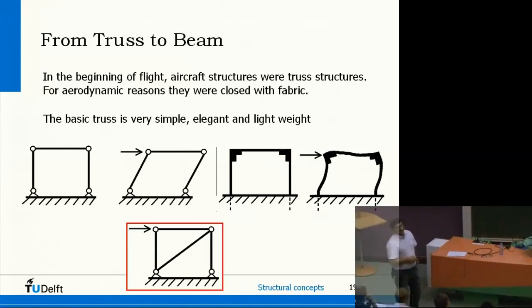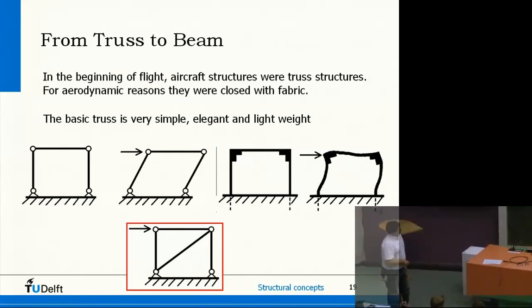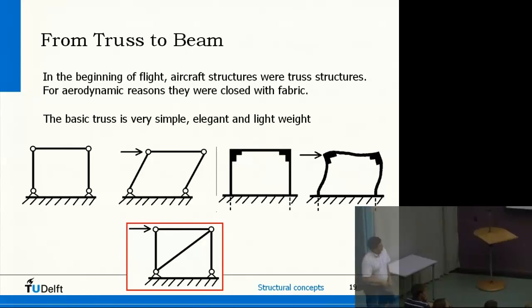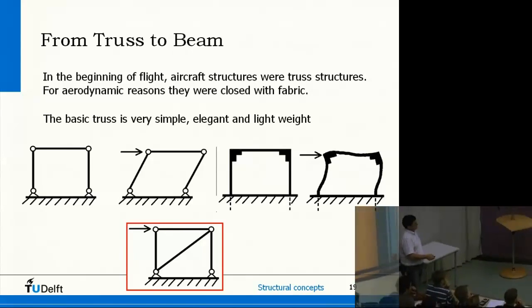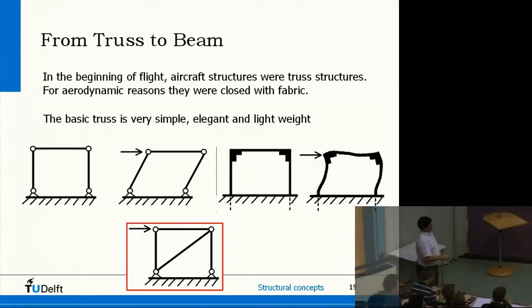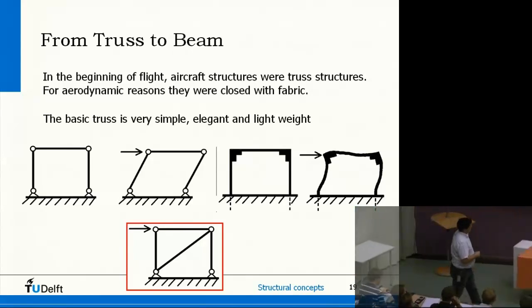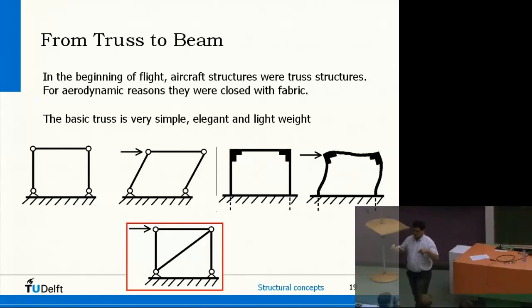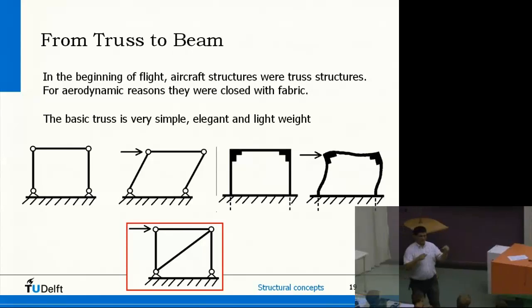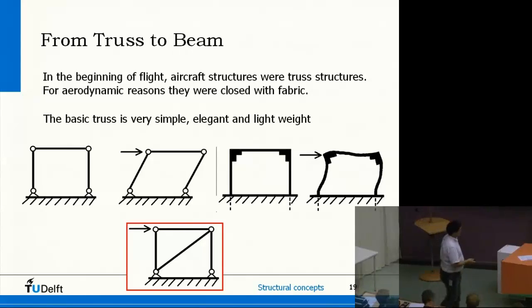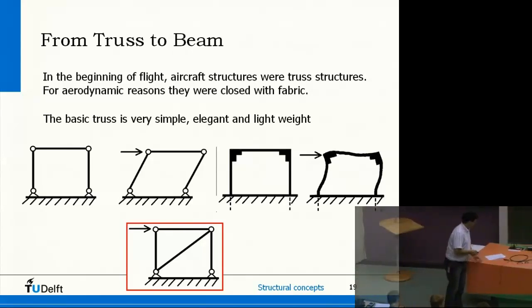So a more elegant way to do it is to put an additional element in there, another beam, another bar, as you can see here. And this is sufficient. Now we do have a statically determinate structure. If you look at truss structures, they are built from elements like these. This is a starting element, and building up you can continue and make your truss structures.